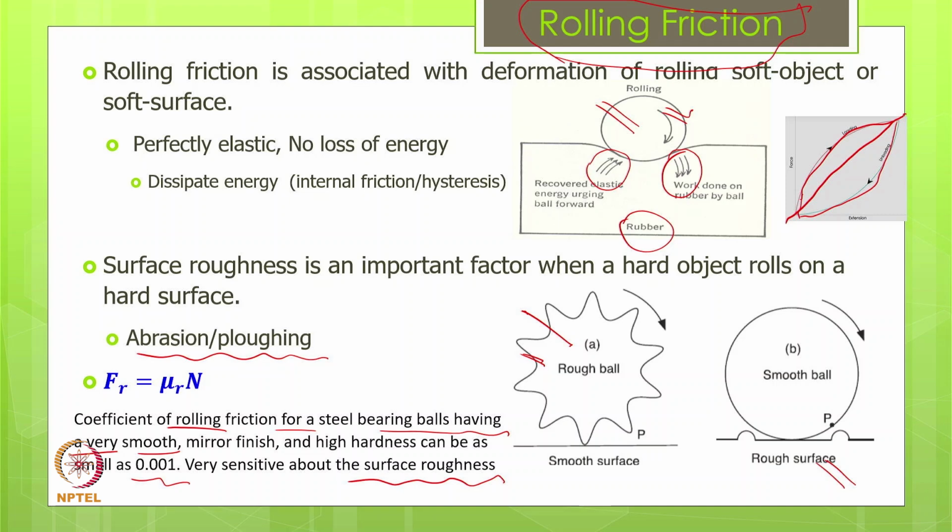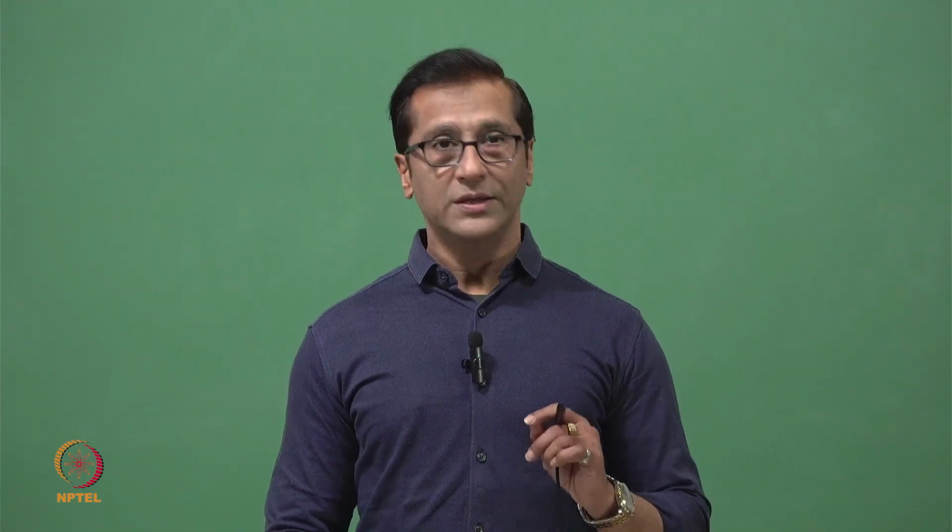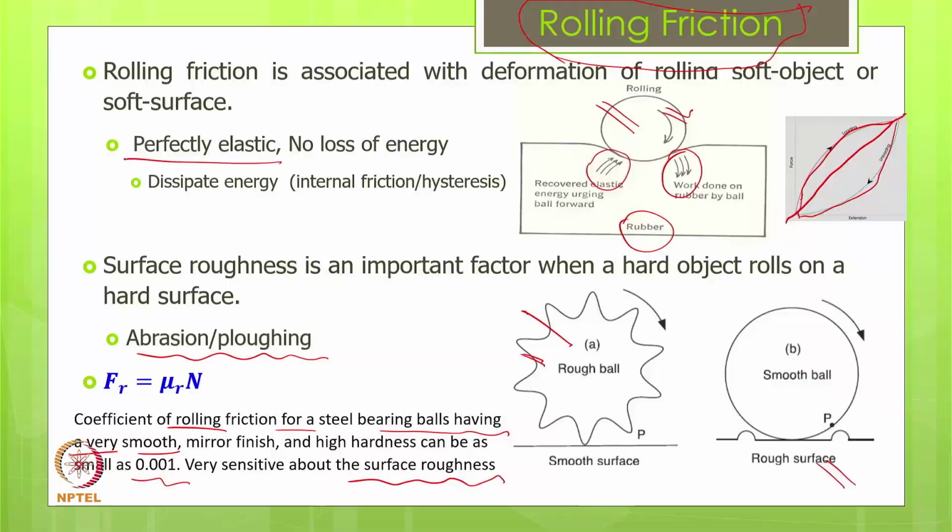It's not then hysteresis. Hysteresis is basically a smooth surface deforming and regaining the shape back. That's what we say is perfectly elastic, and that too instantaneous. However, we know that it will not happen, and we are aware that every rubber material has a loss modulus. For metals we generally use elastic modulus, while when we use rubber, we also use the word loss modulus, that means how much energy is going to be lost after deformation.